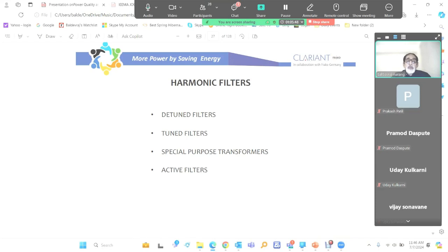So the principle is that here we allow the current to pass through a designed circuit, and there we are cancelling the harmonics. Both are effective in their own manners, and there are advantages and disadvantages, and sometimes we have to use hybrid systems also. Many times we can manage with just passive filters, where we are using only reactors. And sometimes the harmonic concentration may be very diverse.